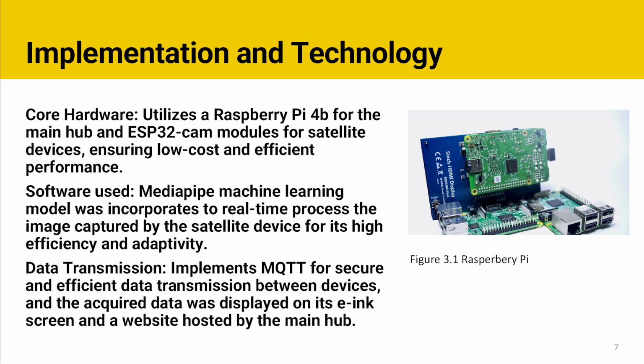And for the data transmission, we implemented MQTT for secure and efficient transmission between the main hub and satellite. The acquired data was displayed on the e-ink screen of the main hub and a website hosted by the main hub as well.